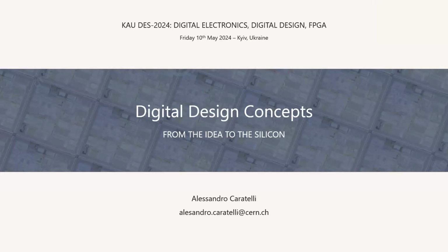Let's start from the point that an FPGA or a processor are basically a particular integrated circuit. When you do an ASIC, you can do an FPGA or a processor. So basically, there is a particular design that is defined for some type of application. When you do an ASIC, you optimize to the maximum for what you want to do with it, so you build a chip which is really optimized for that application. CPUs generally give you quite high clock frequencies, and they can be very efficient for running an algorithm which is sequential.